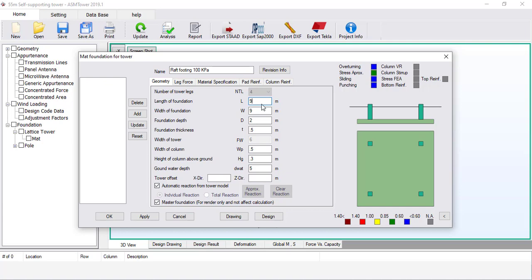Yellow color is our target, because it means safe and economic design. Try reducing the dimensions to 8.5 meters. Still green. Decrease the width to 8 meters and increase the depth of the foundation to 2.2 meters. Good, the stress index is now yellow. Increased foundation depth increased soil weight over foundation and increased contact area between foundation and soil. Thus, the stress on the soil decreased.